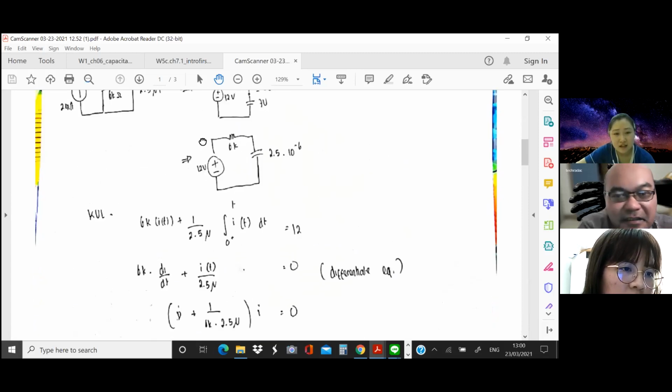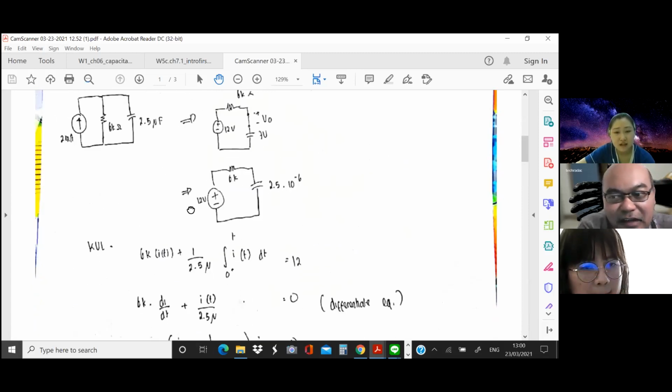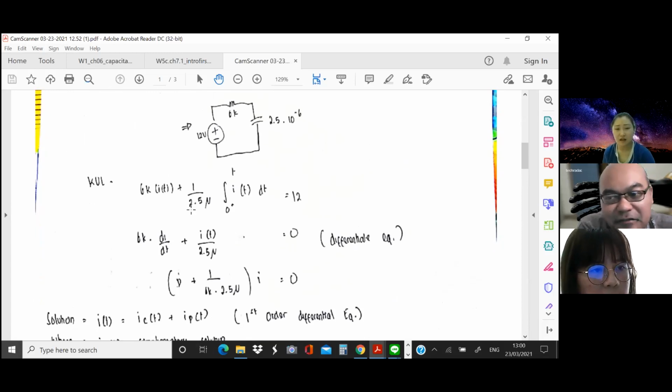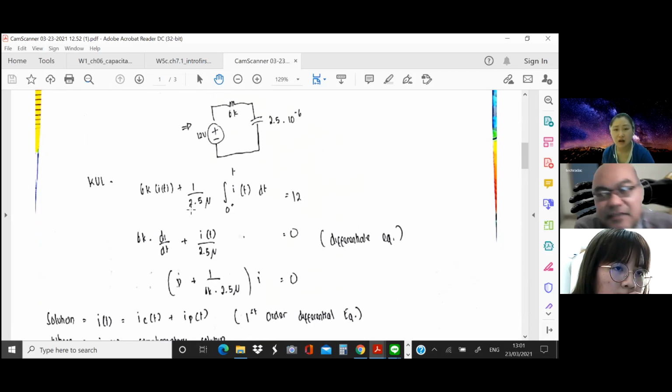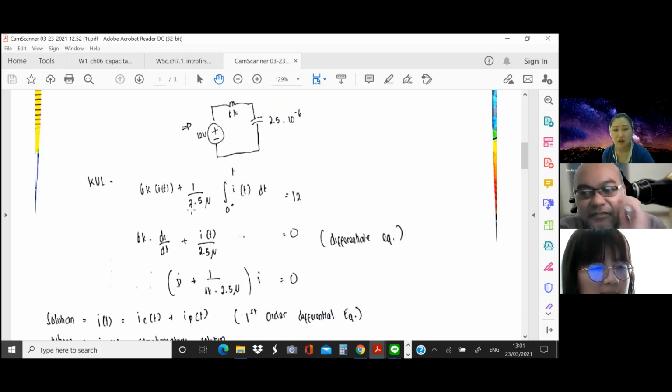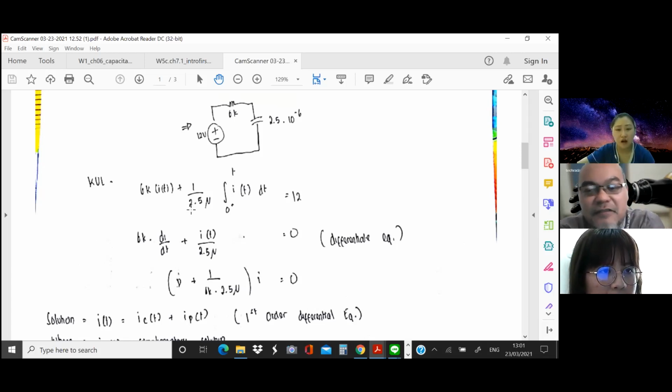We don't immediately calculate tau from the equivalent R times C. You have to first express it in the differential equation, tau dx/dt plus x(t) equals F. From there, you know that the general solution will be x(t) equals K1 plus K2 exponent minus t over tau.